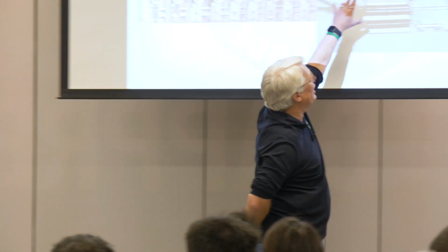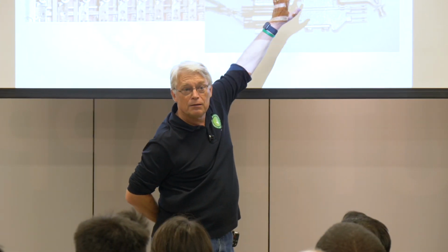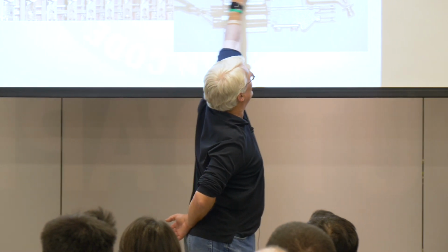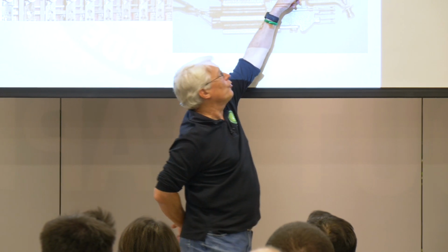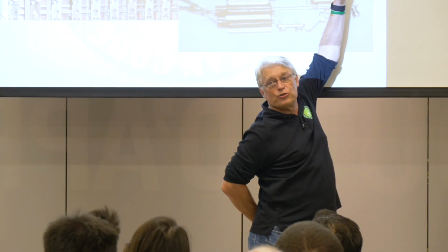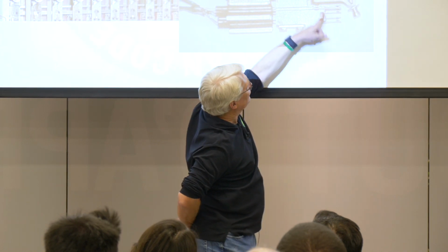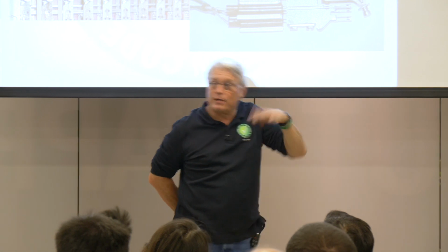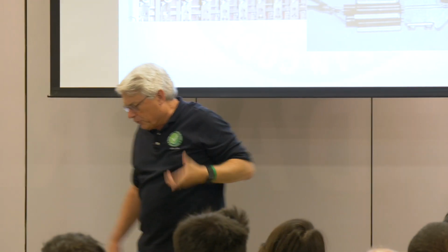The kinds of equipment he was using looked like this. This is a relay. Anybody played with a relay? Relays are fun. They're real simple to understand, right? This is an electromagnet, just a coil of wire. If you run a current through the coil of wire, it magnetizes that piece of metal. This other piece of metal then snaps towards it, and that drives this little lever system that changes the position of these switches. And the switches might close or they might open, depends. If you think about that enough, you'll realize that's enough to do computation.